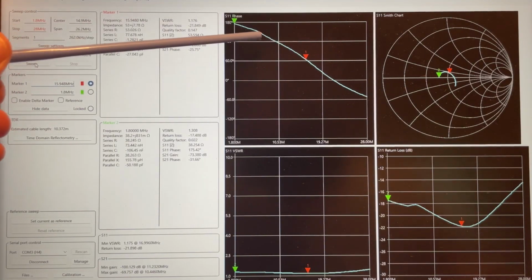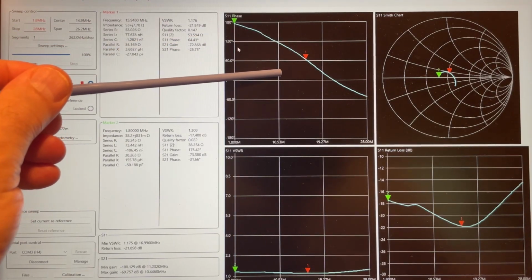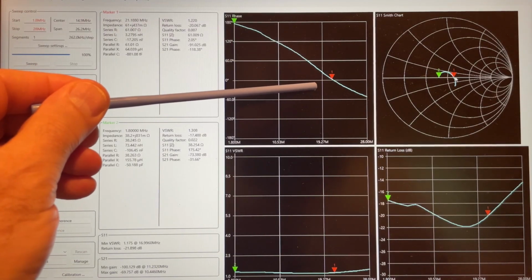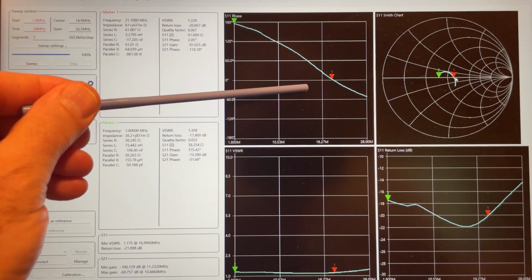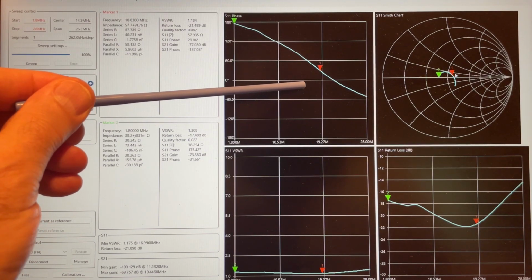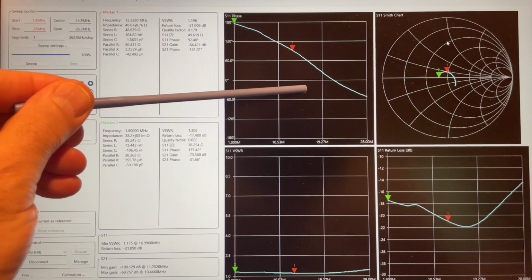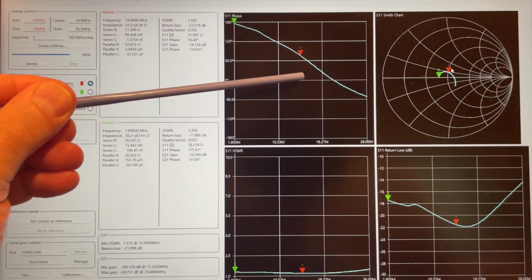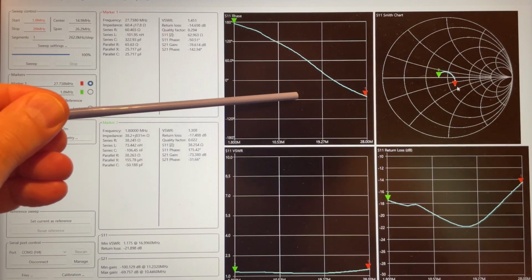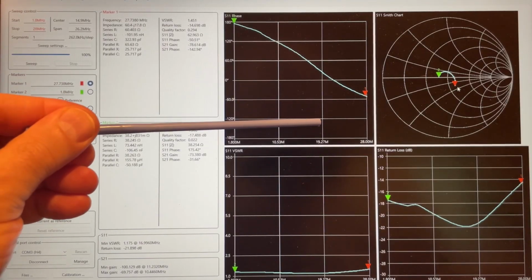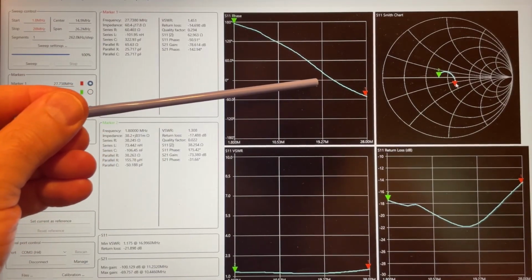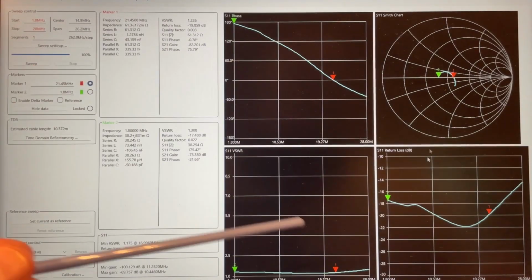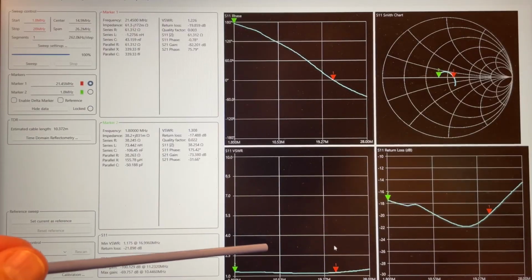And if we look at the phase, what would we expect to see if I just move the frequency to the center of the chart? That's where we're at zero phase. And of course, if we go to the upper half of the chart, which is inductive, it's plus J, and if we go to the bottom half of the chart, it's minus J, and this would be capacitive. So just to look at the phase and understand that a little better. That's the relationship.